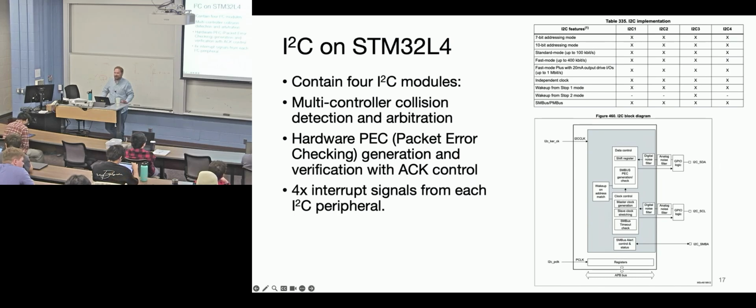All right, what do you think? In the time we have remaining, why would you need multiple I2C modules on one microcontroller? You have 2 devices that have the same address? Yeah, this is a problem. You find some cool sensor, oh, look at this distance sensor. It's really great. I would like to have 50 of them. Oh my God, that would be so great. I'll make a cool embedded system. But the manufacturer's only registered one address. How do you get multiple devices when they only have the same address?